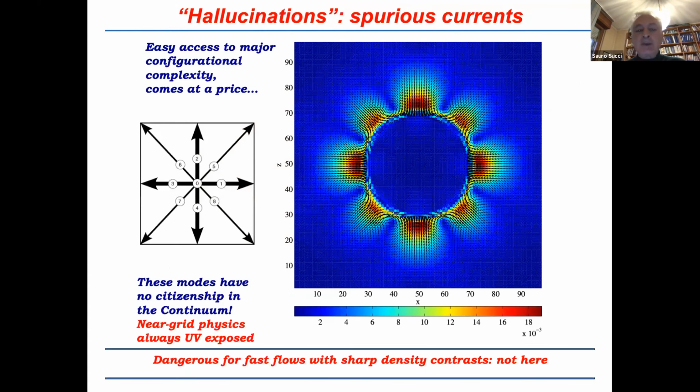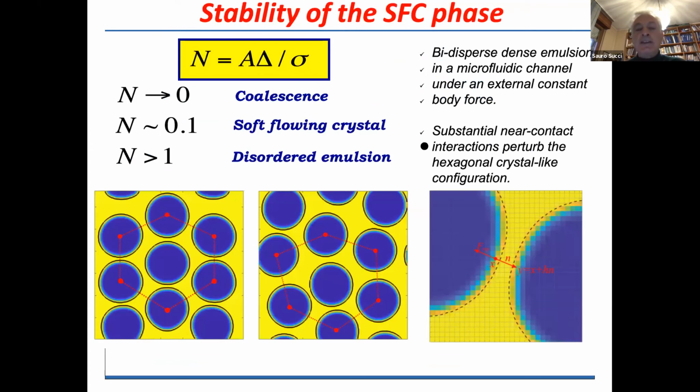I can anticipate the story, and the story is that, happily enough, the Cahn number is, like very often in fluid dynamics, a number which has to be smaller than 1. As soon as it is, say, 0.1, so 1/10, it doesn't really matter if you go from 1 over 10 to 10 to the minus 5, because the physics depends analytically on this number.